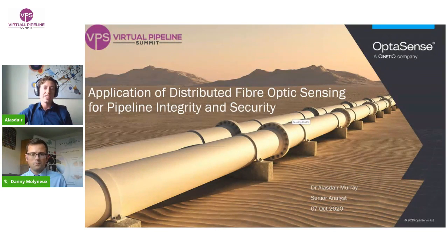However, another point to that is, particularly for liquid leaks, if there is any glugging going on as the liquid exits the system, it will generate further pressure pulses, which will exhibit in a similar manner to the negative pressure pulse. And so there are further opportunities for detection.